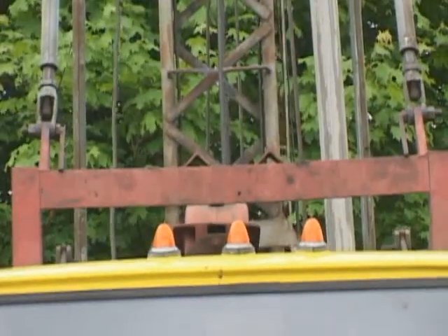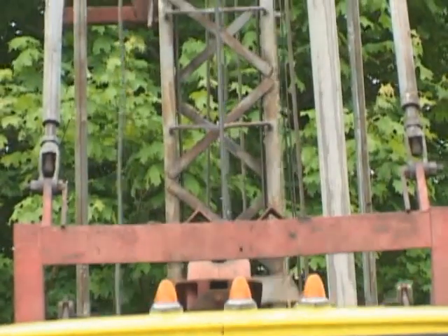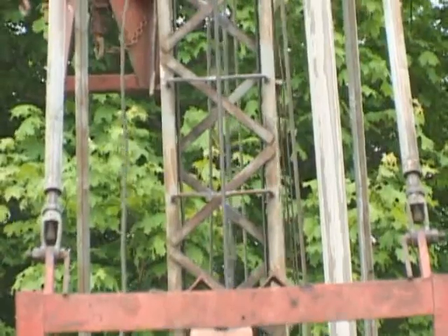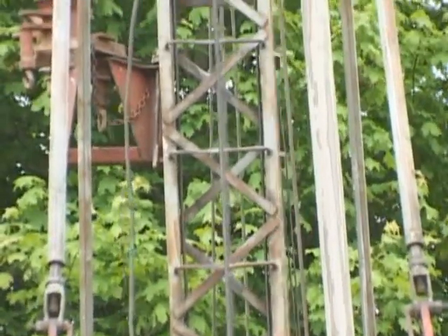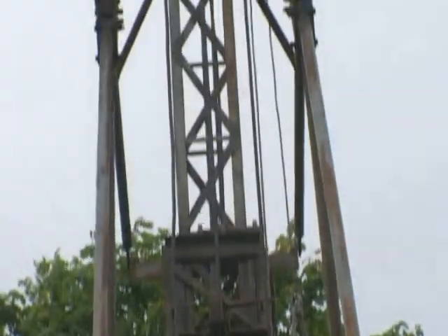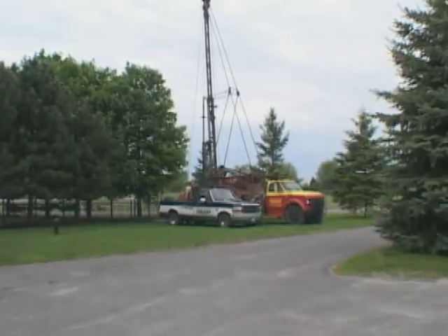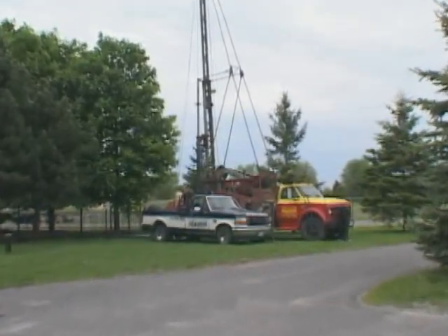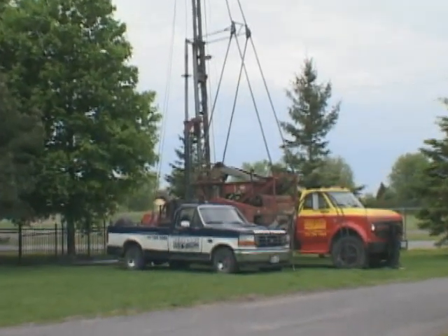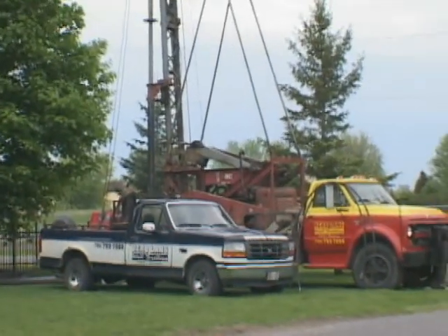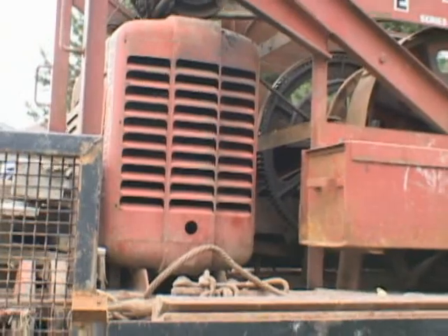These machines are mainly used today for drilling in unconsolidated materials and soft rock formations where relatively shallow depth wells are required, approximately 100 feet or less. Slow penetration rates are characteristic of this drilling system. Support equipment required for this drilling process are basic: a small truck with welding equipment, torches, and a small amount of makeup water. A separately mounted deck engine powers the rig.